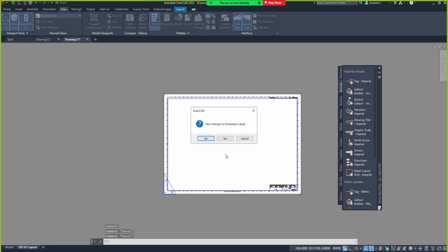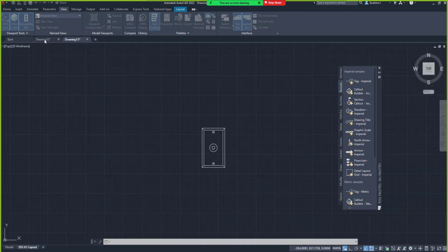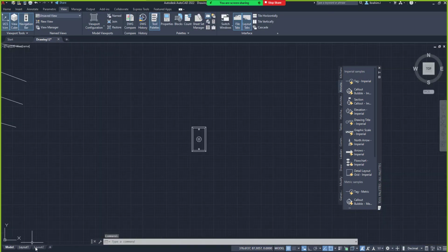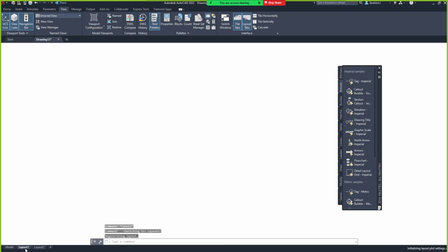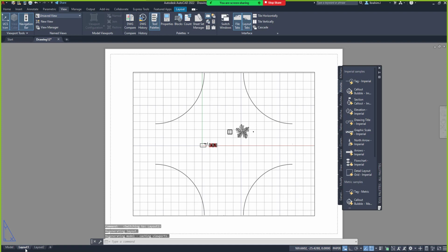Or I can delete even this drawing 13 and go to just the last project that we have here. Did we create these two layouts? No. But they were created by default by AutoCAD. This layout section is where we are getting our design ready for what? Print. Right? This is when we are telling AutoCAD that we are trying to put our design on paper. That is plotting.